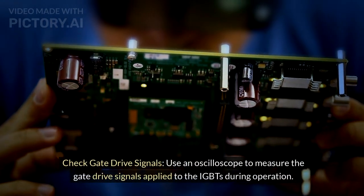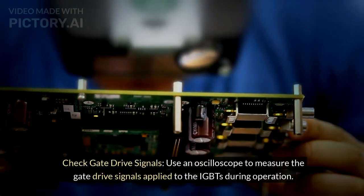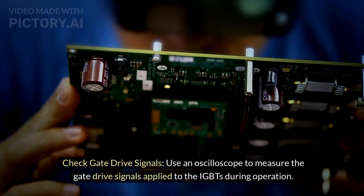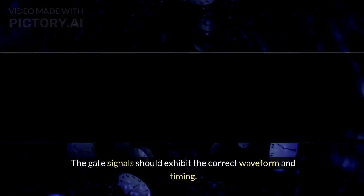Check gate drive signals. Use an oscilloscope to measure the gate drive signals applied to the IGBTs during operation. The gate signals should exhibit the correct waveform and timing. Abnormalities such as distorted waveforms or missing pulses may indicate a problem with the gate drive circuitry.